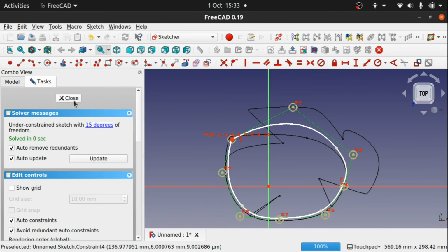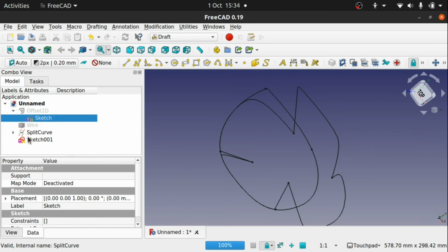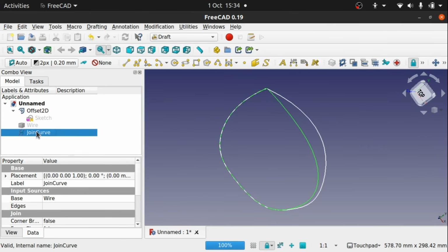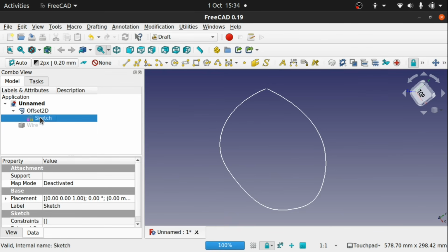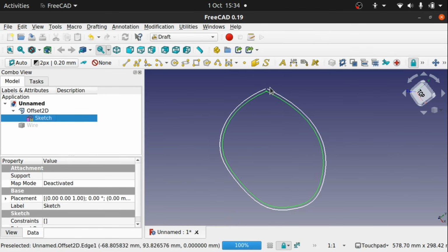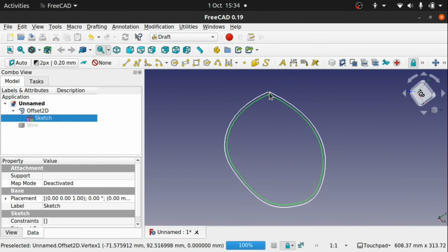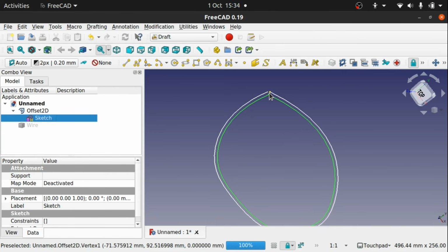But if you're not looking to convert back to a sketch and you just want to do that offset, then that is sufficient with the B-spline. And also you've got the curves workbench tools to repair gaps in here if you so desire, but that's up to you if you want to use those.